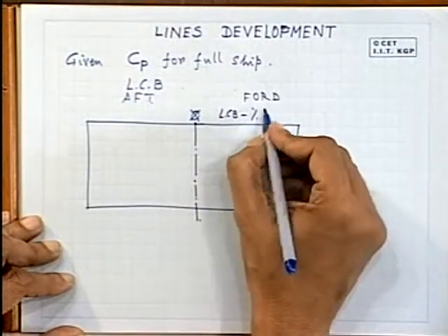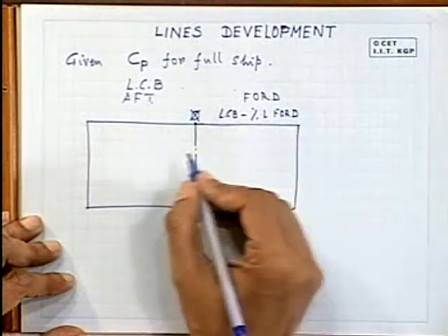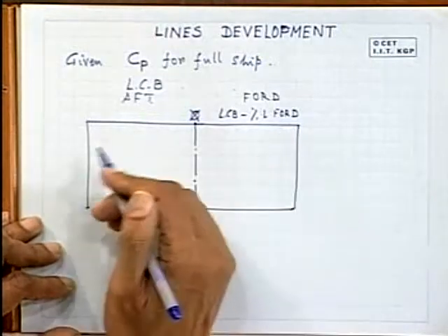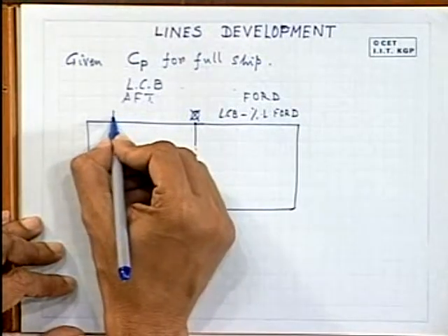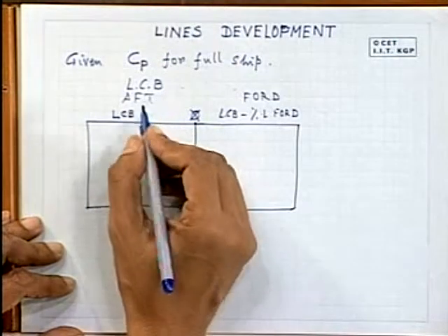If it is percentage of L forward of midship, then you consult the diagram on the right hand side, and if it is aft of midship, you refer to the diagram after the midship line.